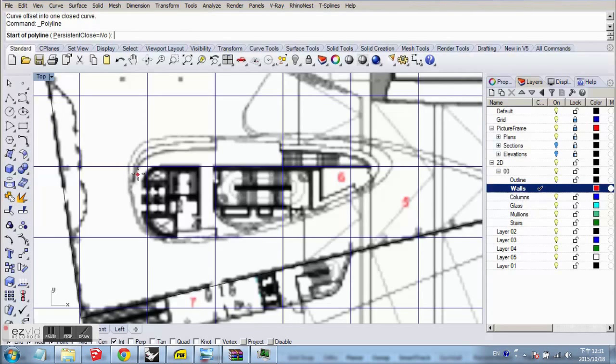straight polyline first. Use the grid intersection as our start point. Stop a little shy of the corner. And now, let's draw the bottom part using a control point curve. Draw it until the left and finish it up with a small straight line piece.